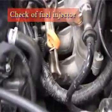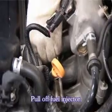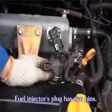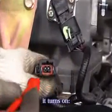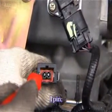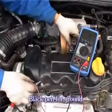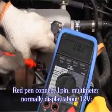Check of fuel injector. Turn off the fuel injector. The fuel injector's plug has 2 pins, pin 1 and pin 2. Connect the black pin to ground. Start the engine. Connect the red pin to pin 1.